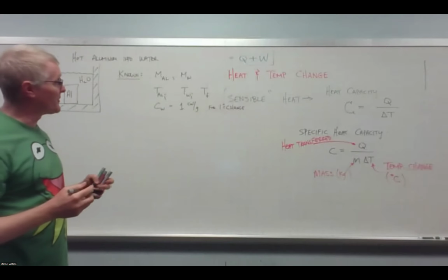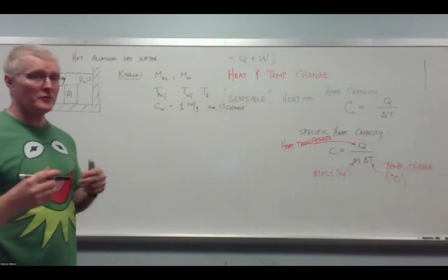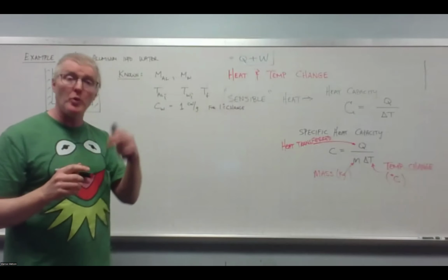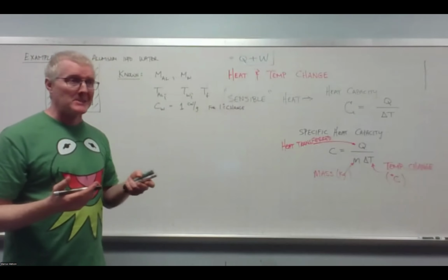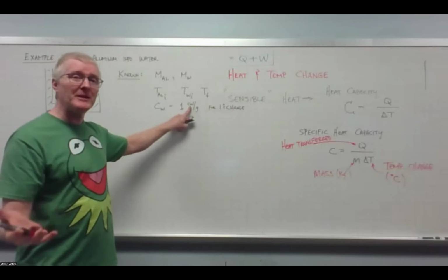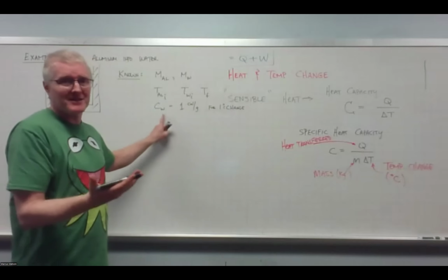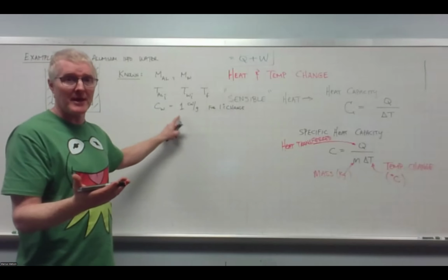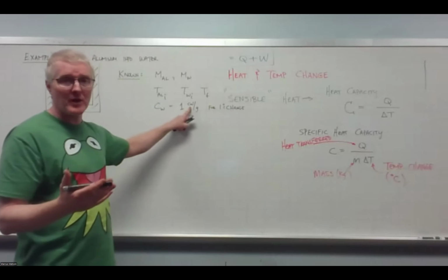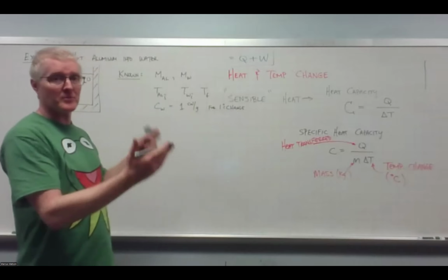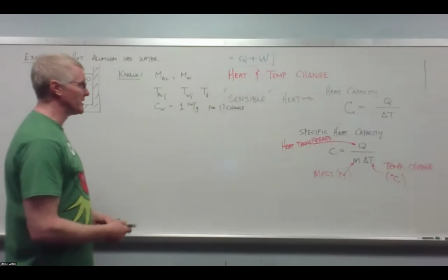Okay. So let's suppose that you remember the mechanical equivalent of heat. Since this was given in calories, and we know how many joules there are in a calorie, then we basically know what the specific heat of water is because it's 1 calorie per gram. And therefore, if I know how many joules are in a calorie, then I know how many joules it's going to take to raise the temperature of water by a degree.